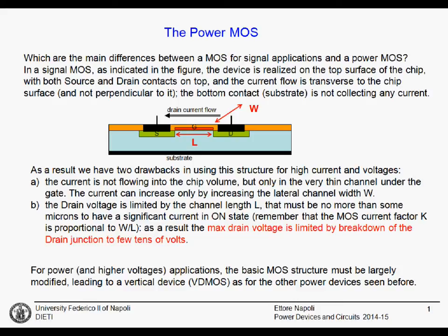Progressing in our studies of the power devices that we can find on the market, and the basic topologies and technologies that we can use, we are now moving to the unipolar side. Up to now, the devices were all bipolar: PIN diode, bipolar junction transistor, thyristor in its two variants, the SCR and the GTO. Bipolar devices usually have higher current capability.